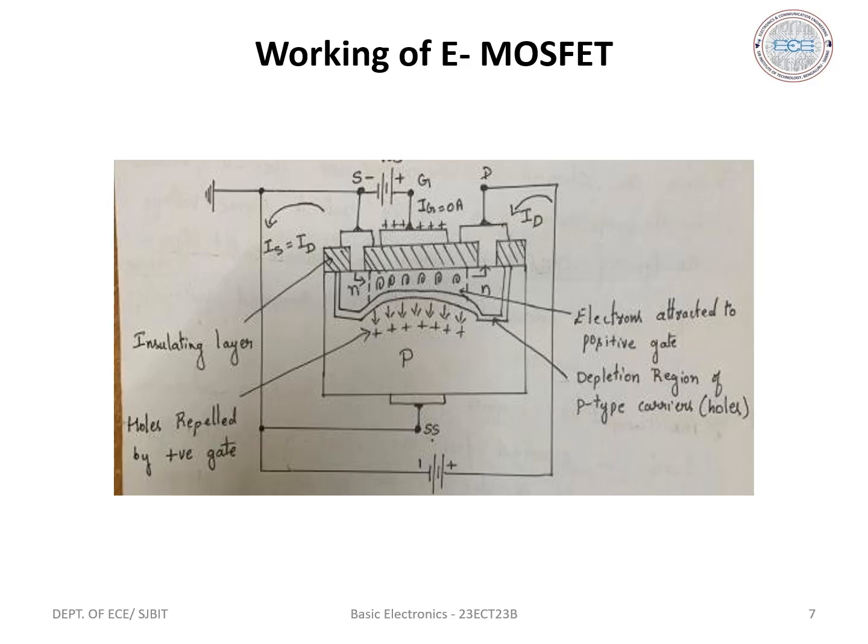At a lower value of VGS, these electrons will recombine with majority charge carriers. As we increase the value of VGS, the holes will be pushed deeper and deeper into the substrate, and more electrons move towards the gate terminal. But as there is an insulating layer here, the electrons are not able to cross the oxide layer.